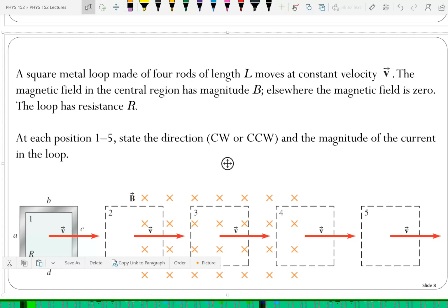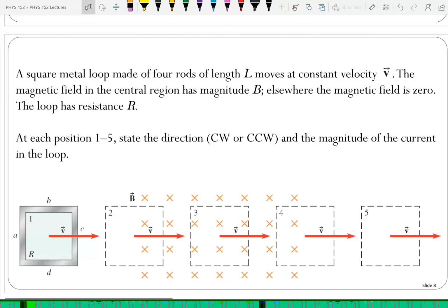Now, I'm not going to call anyone for this. I will explain the answer. In this case, this side is moving into a magnetic field. Moving in a magnetic field, you're going to have an induced EMF. The electrons are going to be pushed, right? If you do V cross B, V is like this, B is like that, you have upward for V cross B. Since it's electrons that can move, electrons are going to go down. A current is going to flow upward.